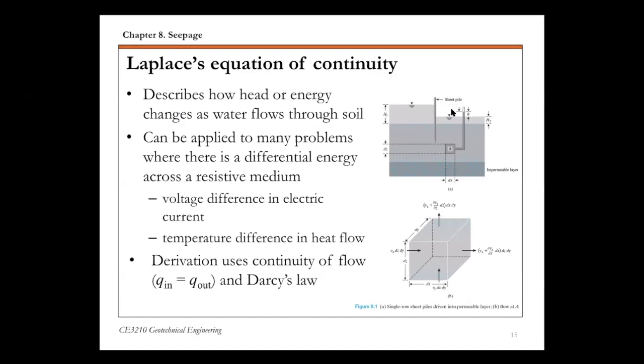And I'm going to skip the details of the derivation here. It's pretty straightforward to derive the Laplace equation. Basically, if you look at this picture at the bottom here, this is a small soil element A taken from this soil media from this seepage problem. And this derivation uses continuity of flow, basically what flows into this soil element A, so that's your inflow, must equal what flows out, so that's your Q out along the X and Z directions.